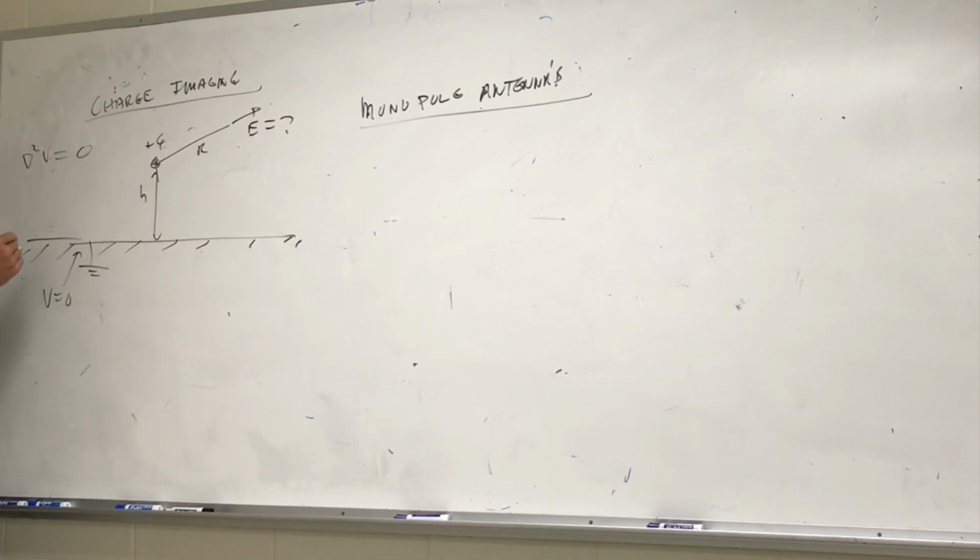And then when you solve that, to get the E field, you would have to say E is equal to minus the gradient of the potential. Do you remember that from EMAG 1? V is a scalar, but to solve that, it's the second derivative of V with respect to x squared plus the second derivative with respect to y squared plus the second derivative with respect to z squared equals 0. Actually, it's equal to a delta function that occurs at this point.